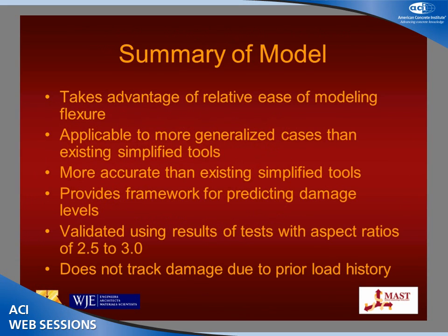In summary, we're taking advantage of the relative ease of modeling flexure compared to shear and strain penetration, and we developed this by using a flexural analysis. It's applicable to a very generalized case as opposed to the existing tools, which have been primarily for rectangular walls. We are more accurate than the existing models. We've developed a framework for predicting the damage levels and validated with tests with aspect ratios of 2.5 to 3. One downfall of this approach is that we're not tracking damage due to the prior load history.